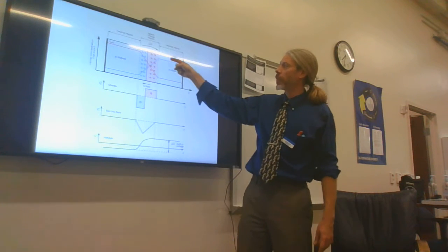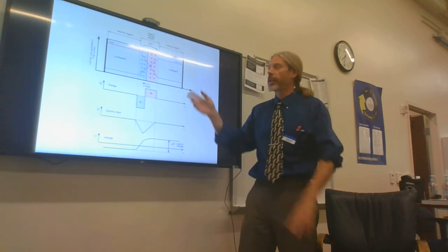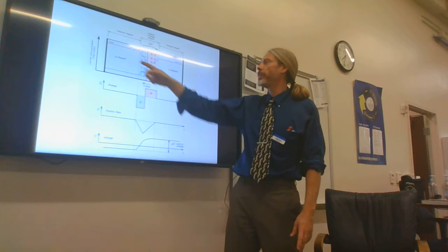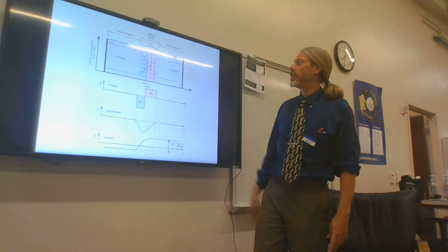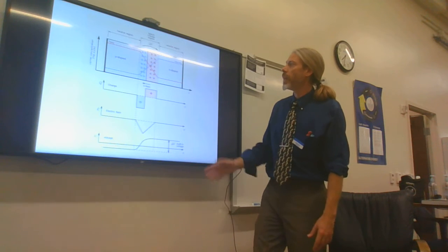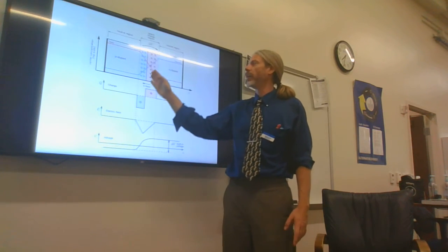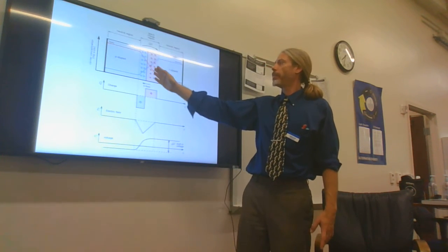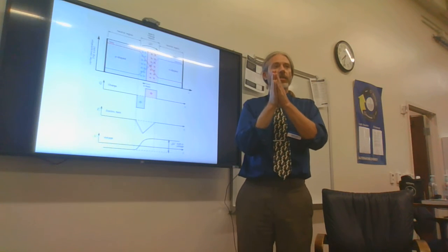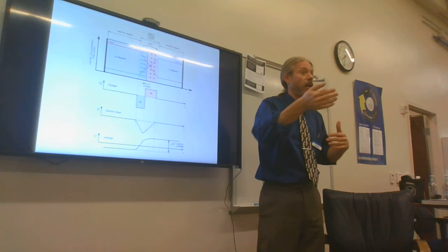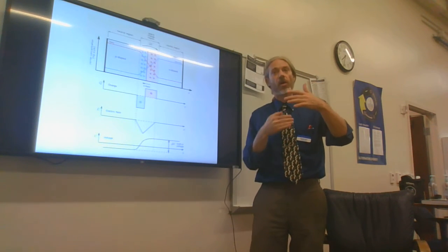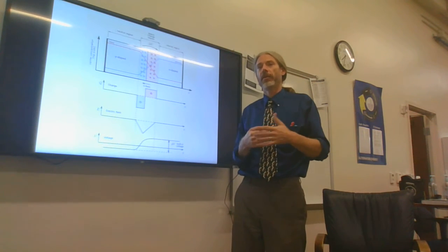All of the electrons, once you put these two things together, cross over and go into the p-doped region, and all of the electron holes come over to the n-doped region. And so you end up with having a whole lot of negative charge and positive charge right next to each other. Basically, almost like a magnet. You have a strong pull on one side and a strong opposite pull on the other side.